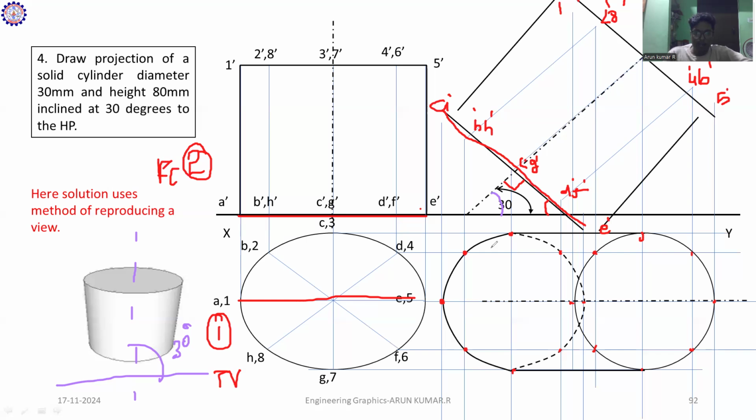I told you one shortcut here: 60 degree. If 30 degree is mentioned, you proceed with 60 degree. If you have 60 degree, then you subtract it from 90, that is 90 minus the angle given in your problem. And you declare this is my third view. This third view we call the tilted front view. What about the last case? You project downwards, then you have to project horizontally, then you consider the final view. This is my final elevation. That is the final plane of this diagram.